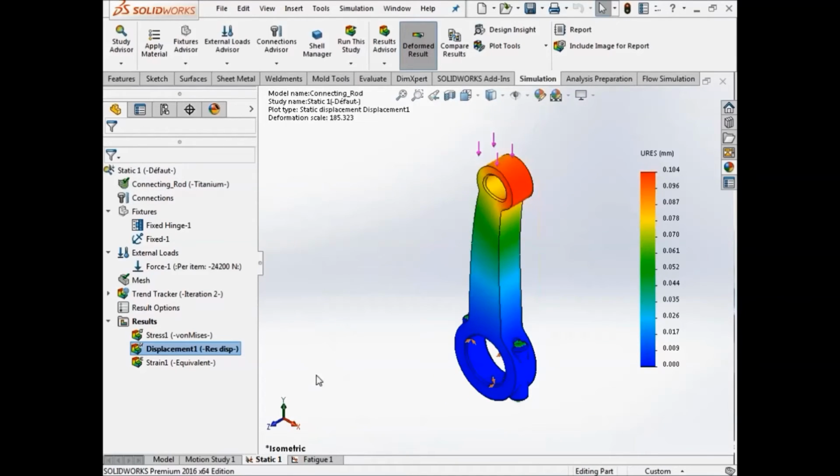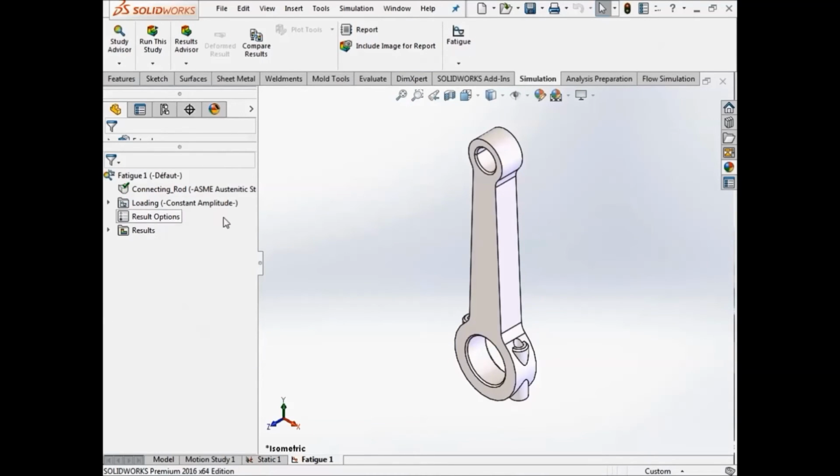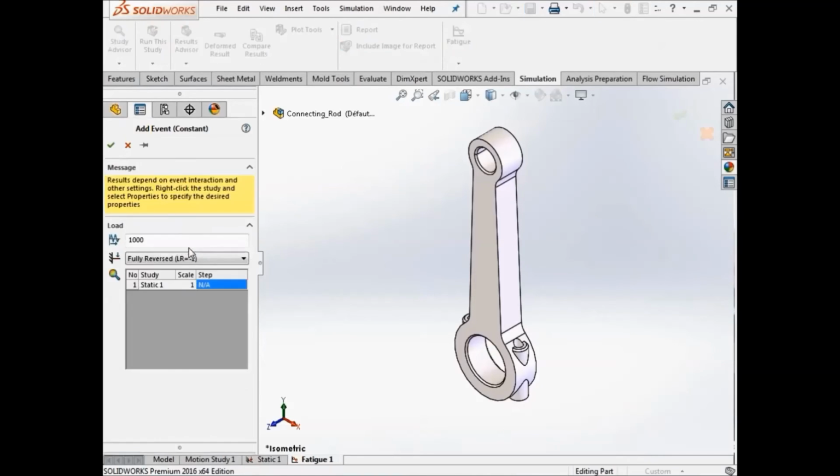So in the similar loaded condition, I'm simply going to study how much life this connecting rod is going to exhibit under this particular load condition. So I'm using the fatigue analysis to do this. Here the fatigue is being studied with the event-based loading condition. I'm directly linking the stress study to this, and I'm simply going to study for 1000 life cycles. The user can directly or manually write the number of cycles to study the load peaks.